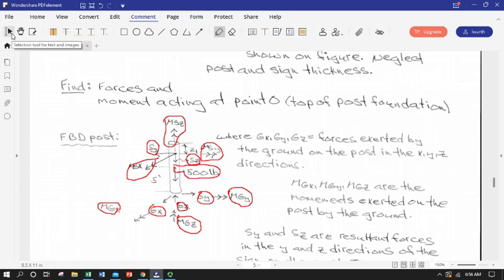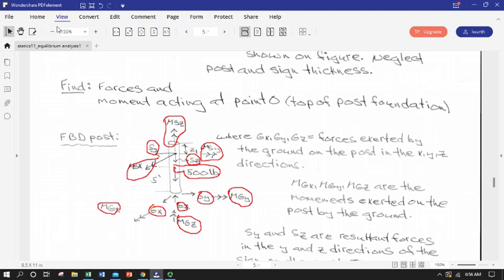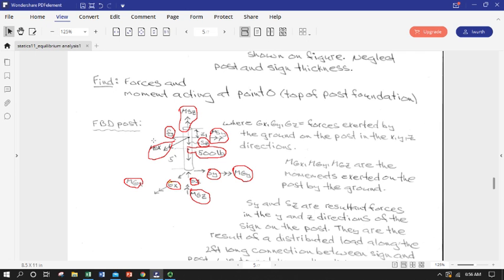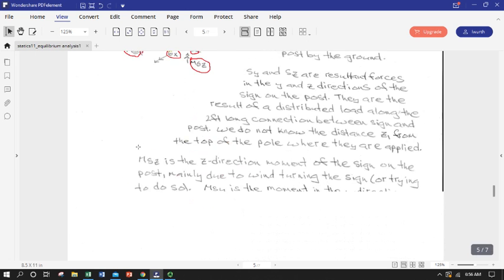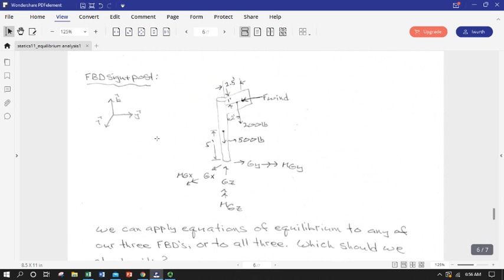Okay. So again, we'll get 6 equations of equilibrium. We've got 6, 7, 8, 9, 10, 11 unknowns. So we could get some relationships out of this, but we couldn't really solve for anything, unfortunately. But we could have a good start on things. Okay, so we're basically collecting FBDs and looking at how many equations we'd have to solve, scoping the math.